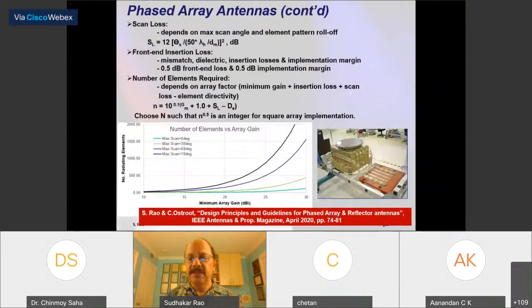This is the phased array on the right side, the advanced EHF uplink phased array at 45 gigahertz. You can see it has about 400 horns. The horns are about 3 wavelengths in size or spacing. What you see on the top is a thermal cover protecting from temperature variations.